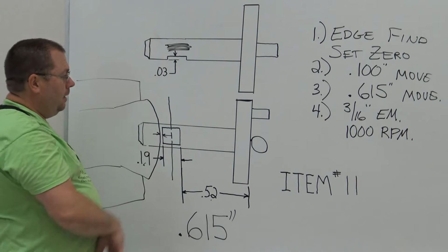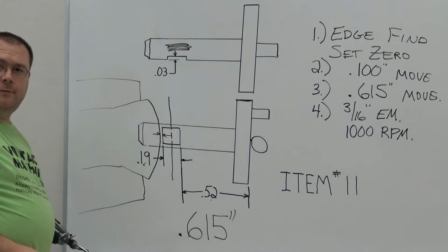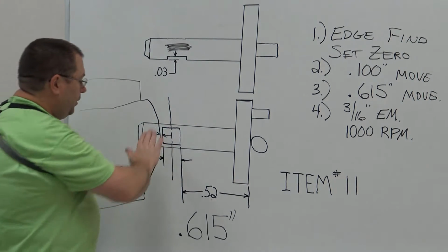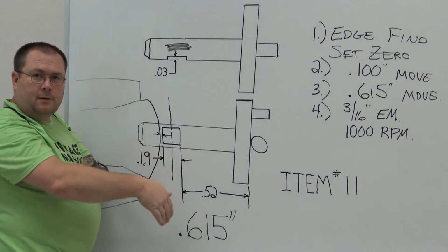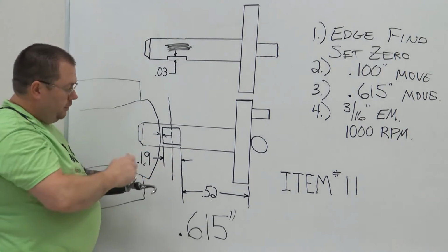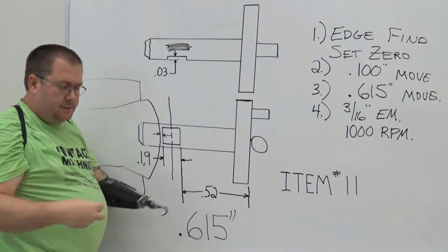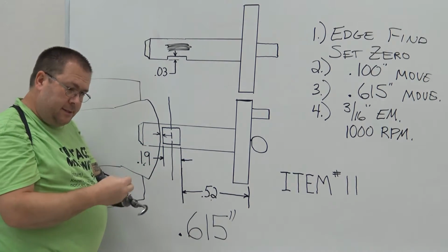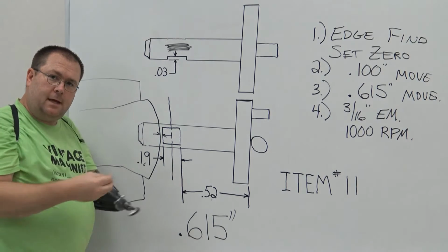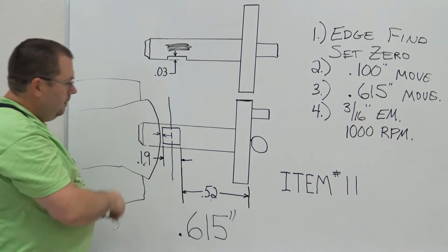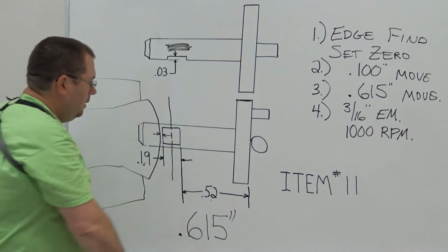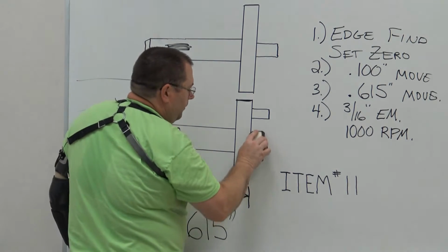Once you get that done, you can take this whole assembly off, deburr over the top. I like taking a file over it while it's on the machine, and then you can take some emery cloth, and as long as the outside diameter is going to fit inside your flywheel, that's all you really care about. Okay? That part's finished. Well, let's back up.